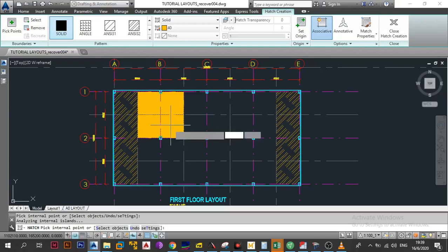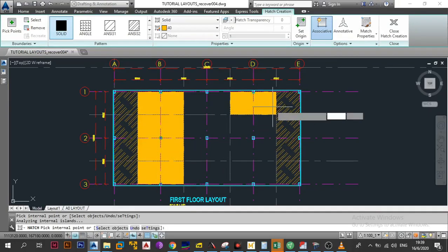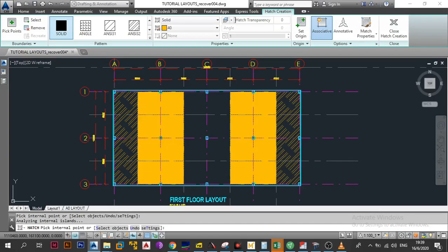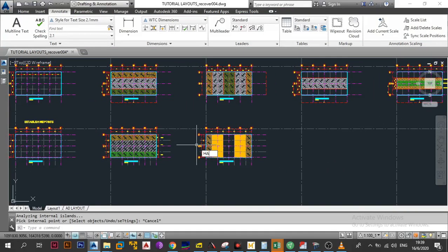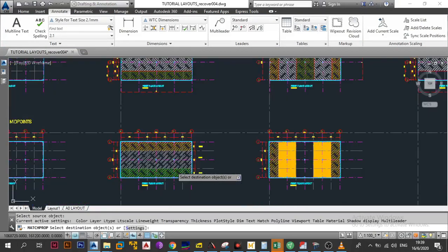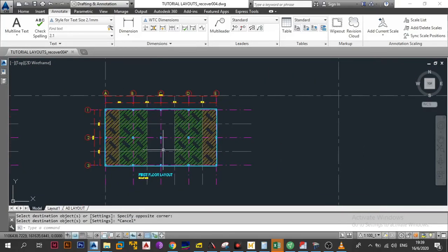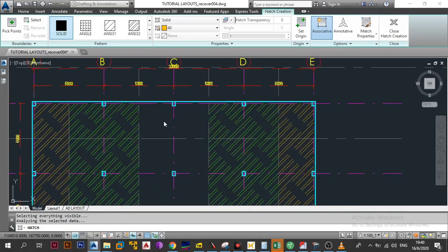This is how you're establishing the slab strip. This is one slab strip, and this is another slab strip, and just remember, in this case, the color does indicate the difference. So this is just MA to match properties. Get the match properties, then you come back to this point. The next thing you want to do is HA and create. You're now creating the last slab strip.